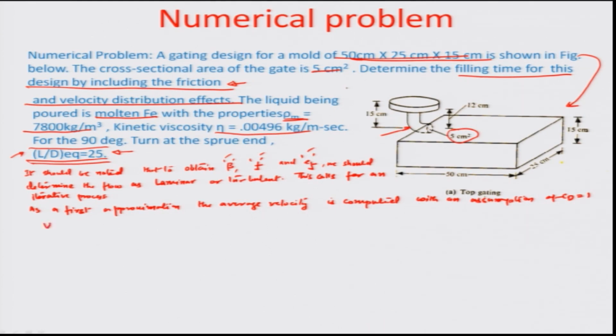So obviously the V3 average velocity would be twice gH, the whole under the root, and in this case, as we had calculated before, the H being equal to 12 centimeters, we have a V3 value which is approximately 1.716 meter per second, and this I think we had calculated in one of the earlier modules where we talked about no wall friction and only an idealized condition.